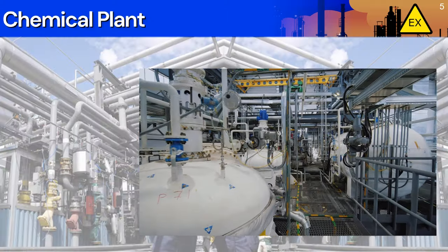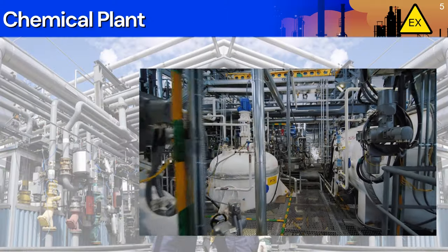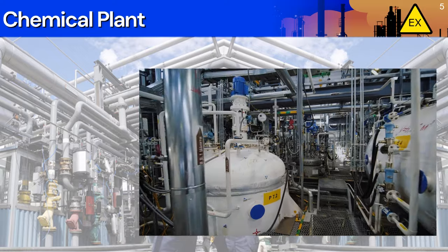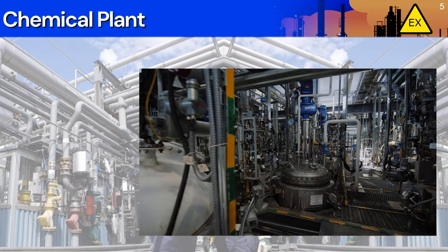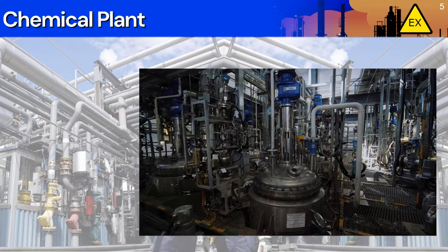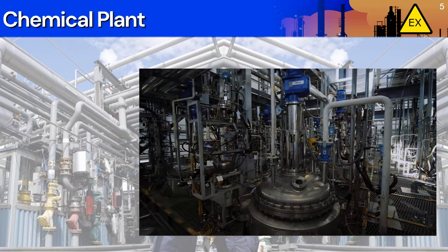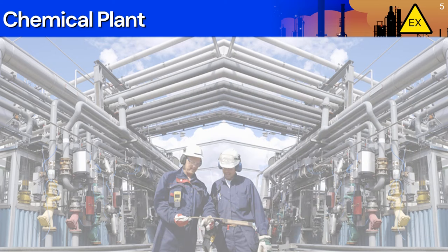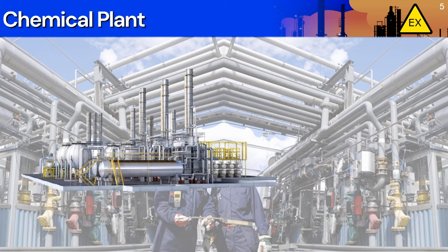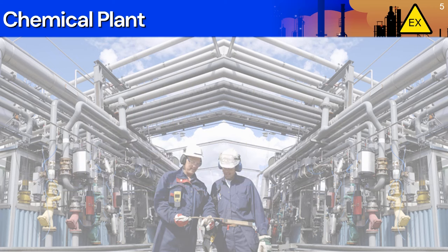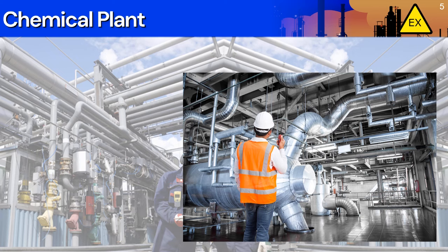In chemical manufacturing operations, a greater portion of the process equipment may handle flammable gases and liquids. The classification surrounding individual release sources will merge to create an overall classified area that may encompass entire buildings or the plot extent. Many processes use a variety of flammable materials, each with their own unique explosion hazard properties. Knowing these properties and understanding their release characteristics is an important consideration.